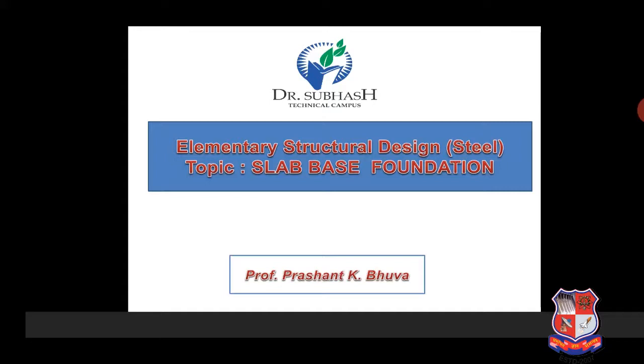So base plates are used for transferring the load from column to its foundation. The base plate reduces the intensity of loading and distributes it over the foundation. So it is an intermediate stage between the column and our foundation, or you can say soil. The load is transferred through the column, distributed, and then transferred to the soil. So the base plate is chosen such that the intensity of load distribution is less than the bearing capacity of concrete on which it rests. So we also know the design of concrete block.